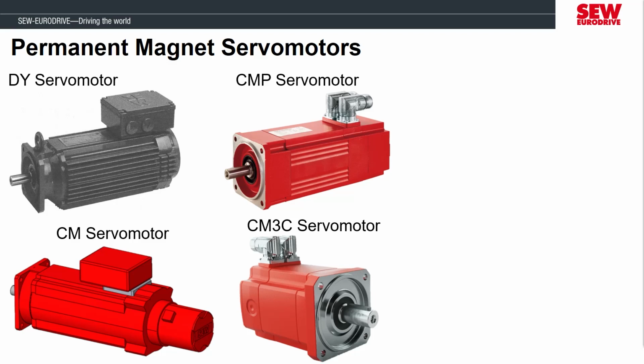The CM3C motor opens up the ability to give the benefits of servodynamics to a higher load inertia application because it has a larger rotor mass than an equivalent CMP motor. However, the CMP motor can output higher torque in a smaller form factor, but with a less massive rotor, which means less inertia. So you do have to weigh the needs of the application to choose between the CM3C or the CMP servo.